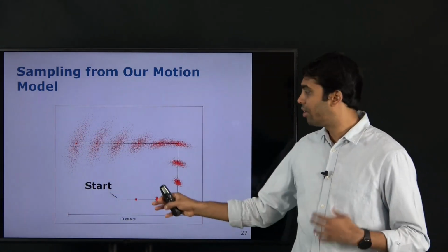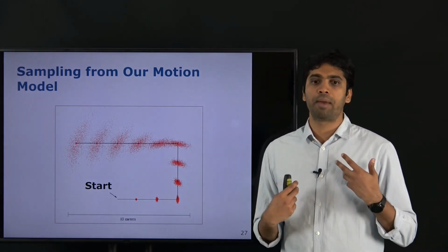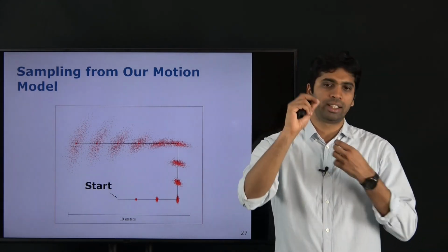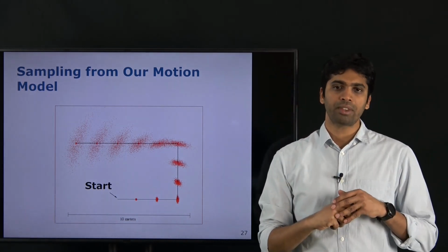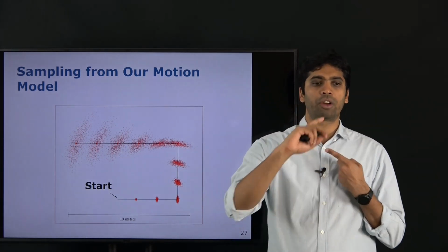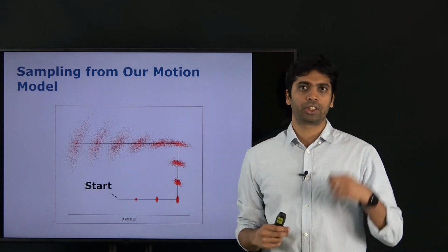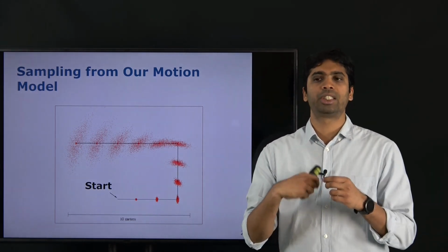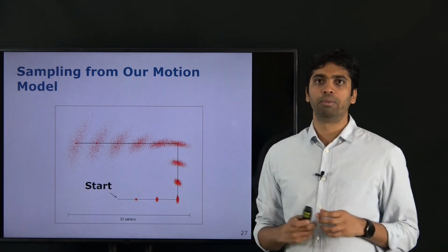We have done this here using the samples idea, but we could have also done the same using the histogram idea, where we would query for each point in the environment or in the configuration space, what's the probability of ending up there. So we've in general seen two approaches. One where we look at each grid cell in our environment and compute this probability distribution, P of x_t given x_{t-1} and u_t. We've also seen a simulation kind of way where we add this noise while doing the movement.